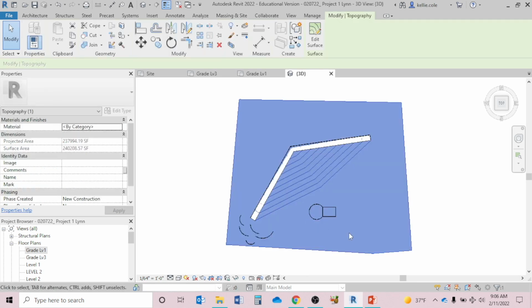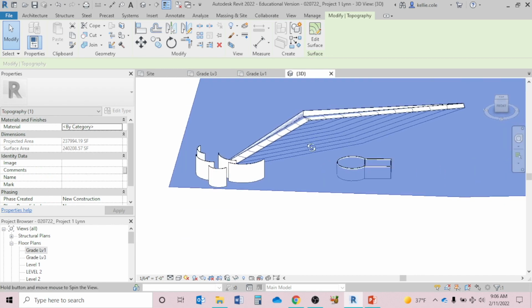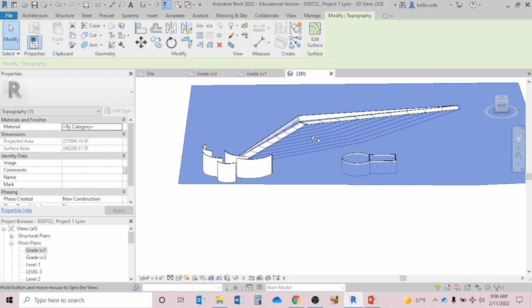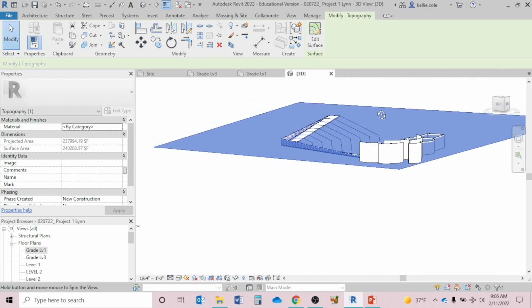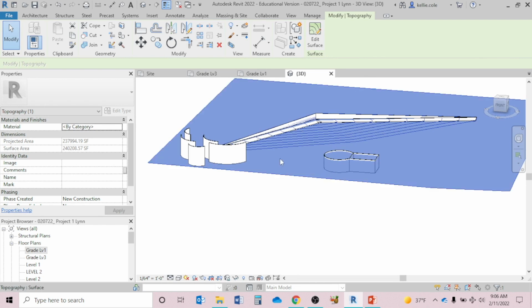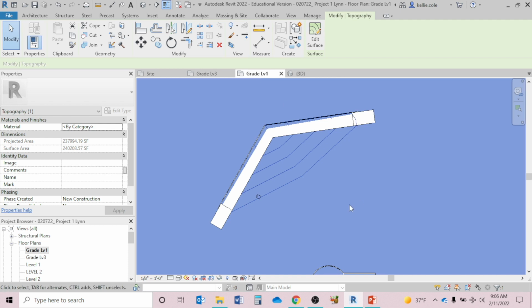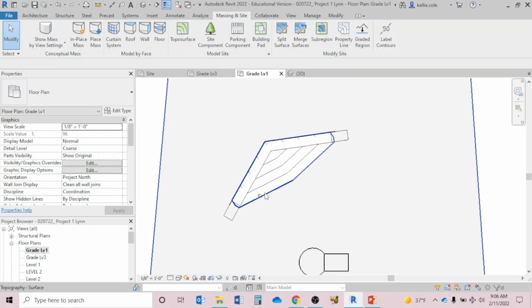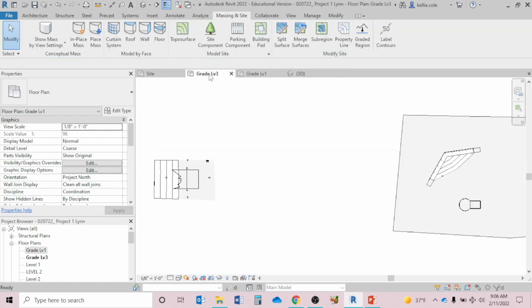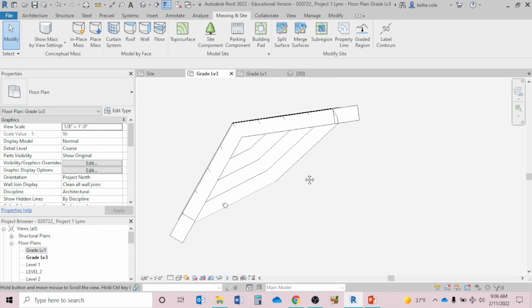Revit does allow us to imagine what it feels like on the site in 3D, but at times that aerial view doesn't quite capture what the feeling of the monument might be on the ground level. So I'm going to teach you camera view. Go to your level 1. Actually, let's instead go to level 2. It gives us a view of the entire thing, and we're at the 9-foot height here.